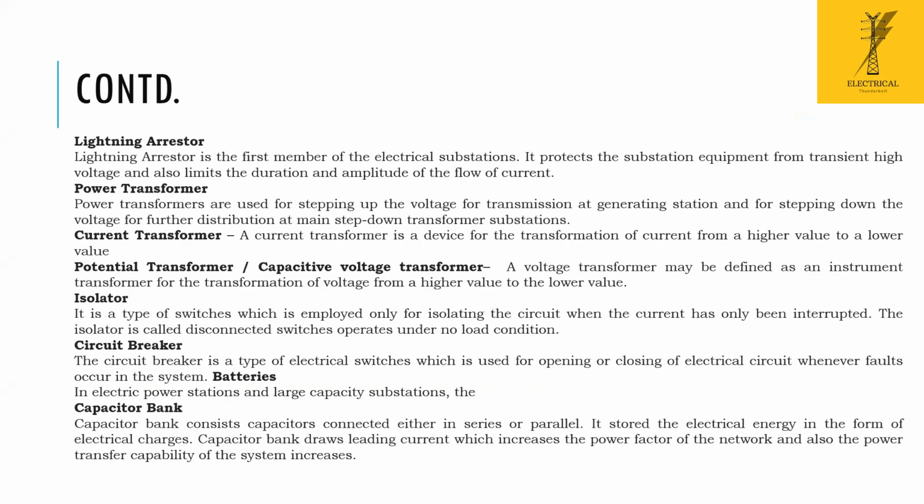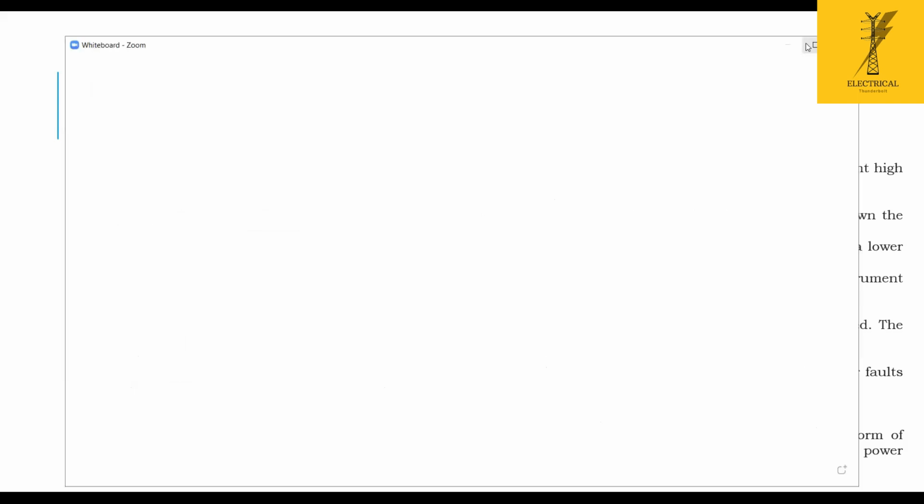Now let's talk about the reliability. For a 200 megawatt substation, as per the guidelines, the industry and developer practices, each 33 kV feeder can carry up to 25 to 30 megawatt of power, as per the economic choice of transmission line voltage.